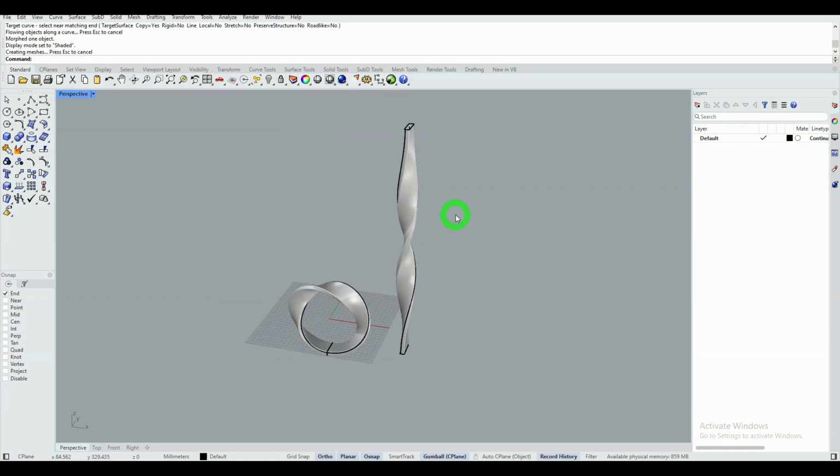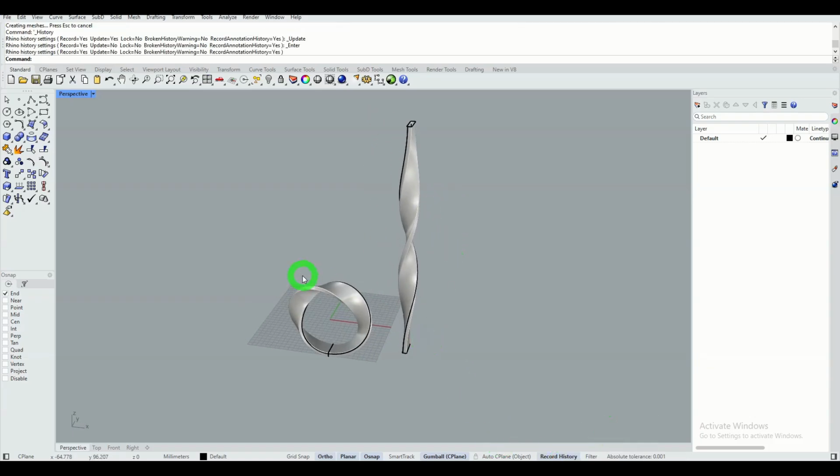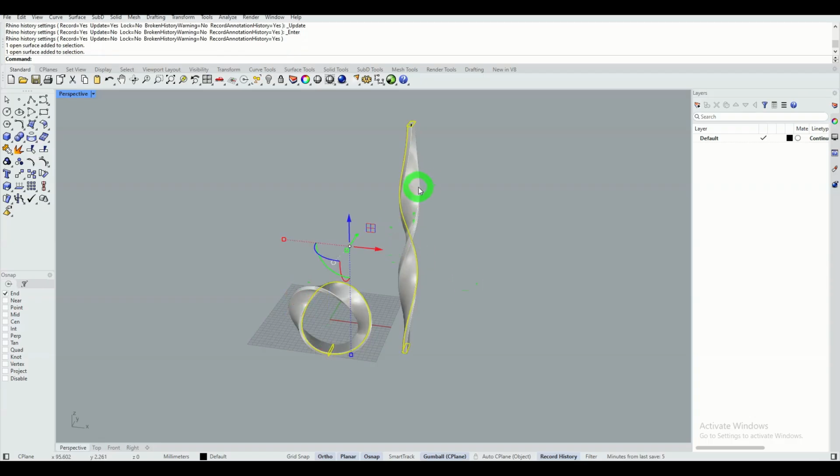As you can see, this is the effect. I disable Update Children. I select the bracelet and the starting object and move them laterally by -150 millimeters.